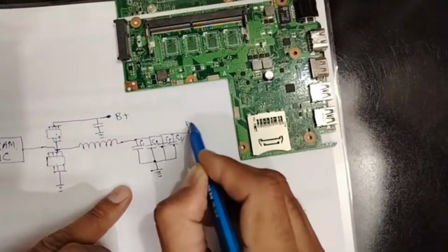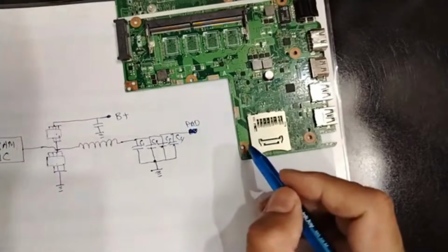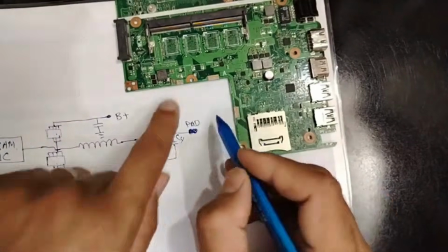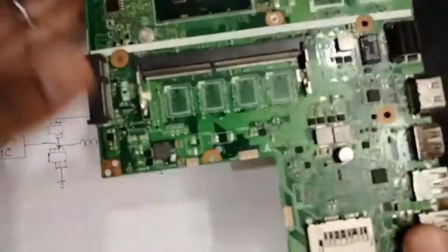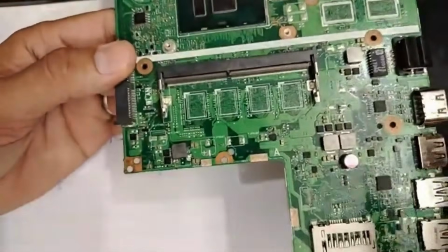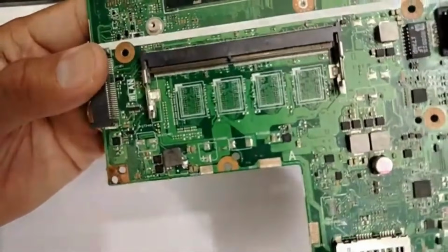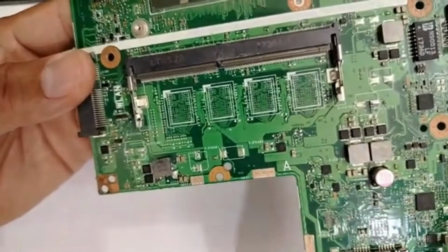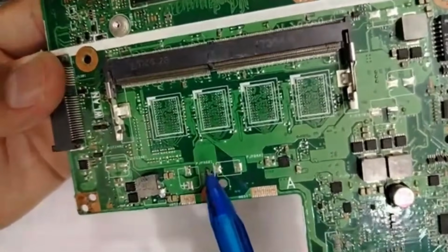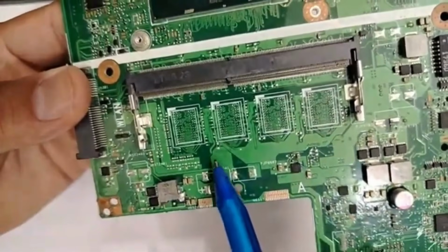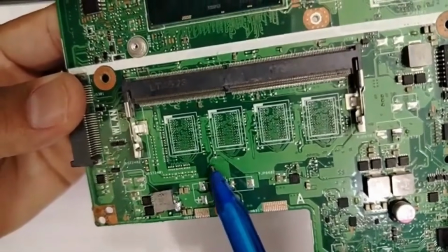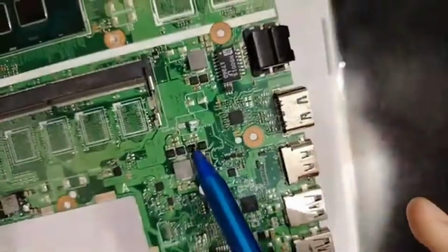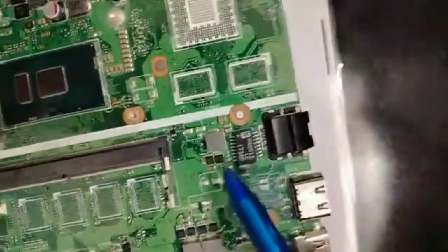This is, we called it, my friend, the pad, or let's call it this point. From this pad, connected, is the problem of short circuit. This is the problem that many beginners and even experts and professionals suffer from. Do you see, my friend, this pad here connected to these 1, 2, 3, 4, 5 points? Five points means every point here is connected somewhere to a circuit. This one connected here, this one connected somewhere here, this one connected somewhere here.